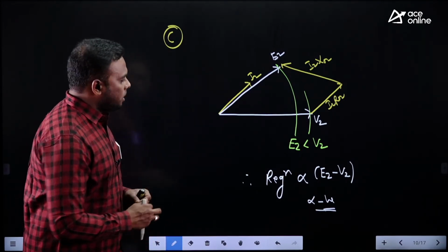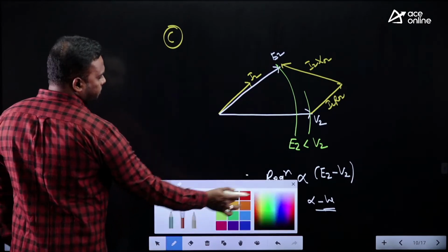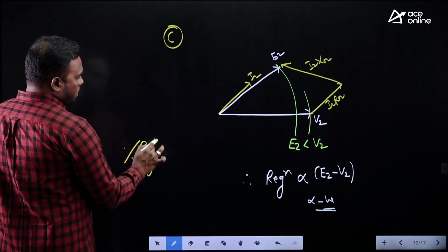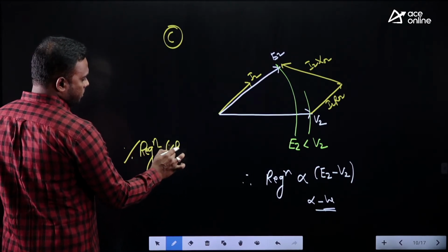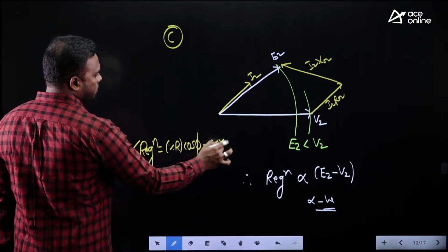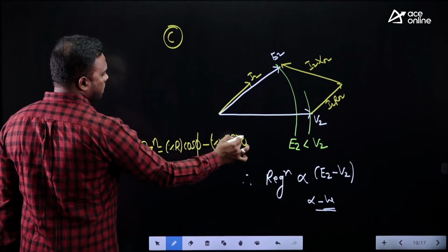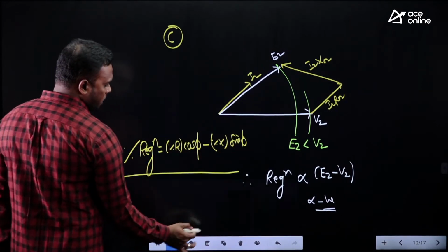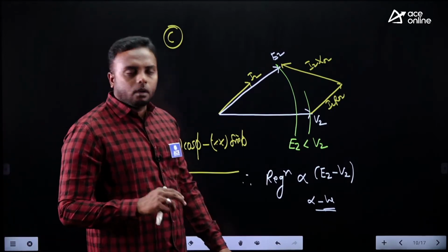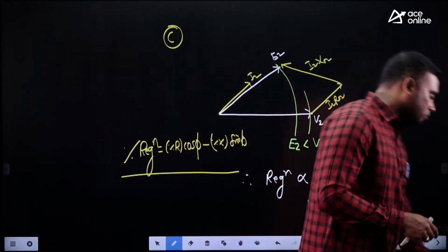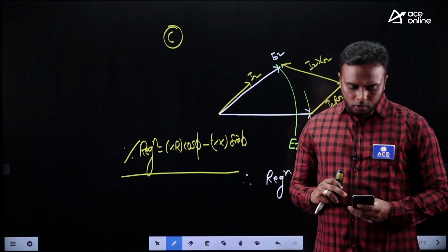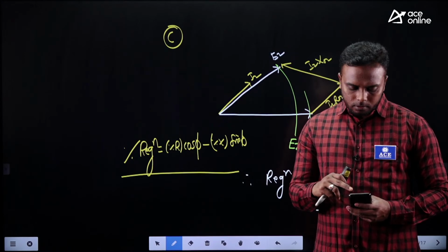Okay. Now the percentage regulation for leading is percentage R cos phi minus percentage X sin phi. So we take minus in the same equation. This is the equation for leading power factor. Now we will combine all these three cases into a graph called the regulation curve. Clear up to here? Any doubt up to this?